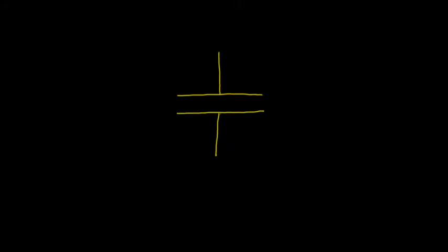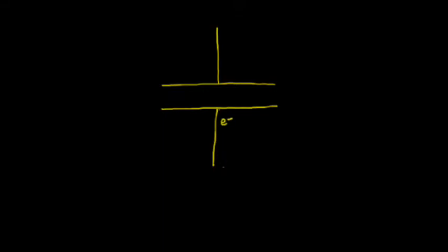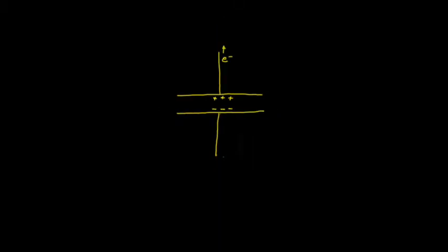There is essentially a non-conducting gap between the two leads of the capacitor, so it may seem surprising that capacitors can carry a signal from one lead to the other. Although there is no continuous conductor, the two plates are close enough to each other that the electric field created by the charge on one plate induces charges to move or rearrange on the other plate. An excess of electrons on one plate will repel a proportionate number of electrons away from the surface of the other plate. The net effect is that current appears to move through the device up to a point.